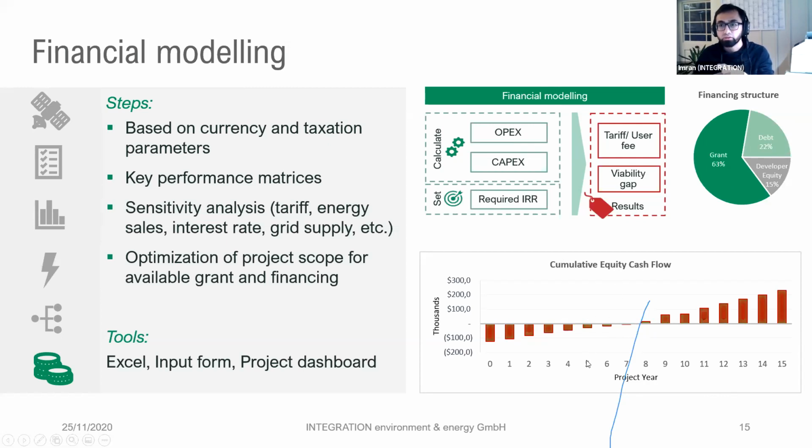One very important thing to say here is that mini grids have been around for a while now. The expectation in the industry is that they are going to reach break even after year 3 or year 4. Unfortunately, that is still not the case. And the sooner we realize this, the better we are able to accept and adapt to it. Project life break-even periods of 7 to 8 years are common, and that is also considering that the OpEx are not running over time. But then you can do sensitivity analysis to see, okay, if the diesel price is changing, what does that mean and how does that impact us?